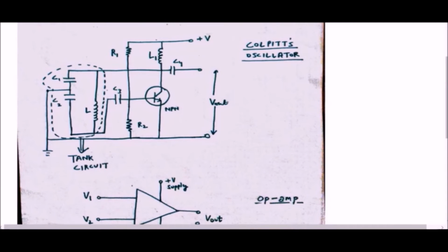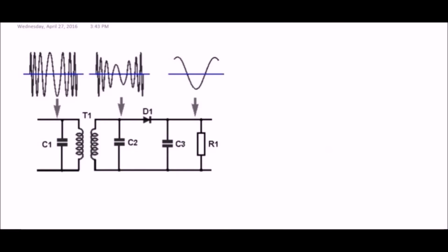Next we will see the demodulator. So when we input an unmodulated wave in the circuit, we obtain an intermediate wave which looks something like this. You can see the parts where frequency is low get attenuated due to the capacitor, as its impedance goes very high, and the parts where the frequency is very high do not get attenuated that much because the impedance is very low. The final output is obtained with the help of the envelope detector, which comprises D1 and C3.